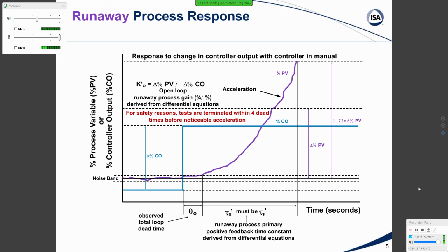Here we're talking about the internal feedback being positive. There's a positive feedback time constant, and when you don't have the negative feedback in a process, the way you achieve that is by having more gain action, more proportional action. It becomes important, as we'll see, in near integrating processes, and that was part of the enlightenment that occurred with going to a near integrating approximation, which we'll see in part 2 of this WebEx Mentor series.